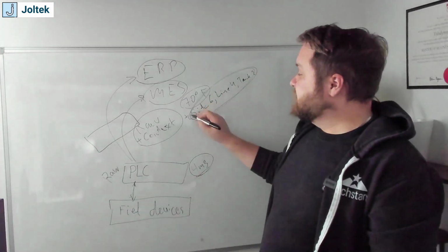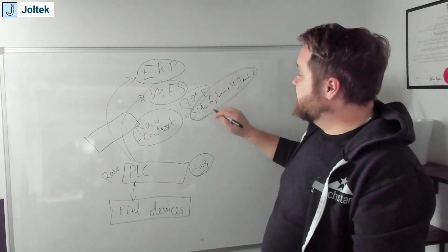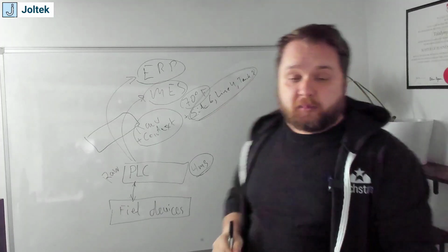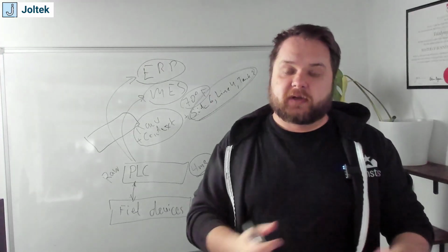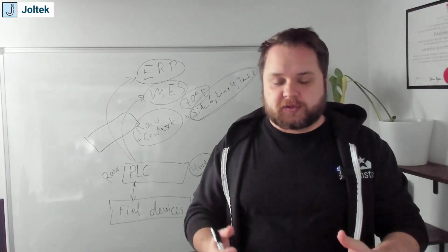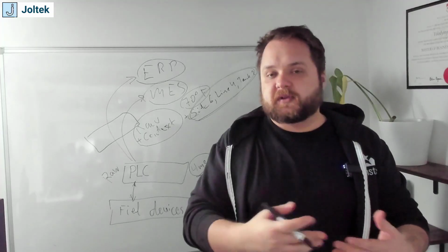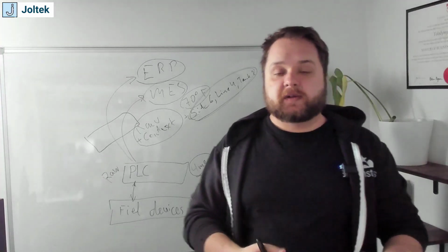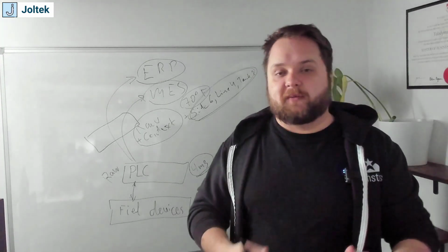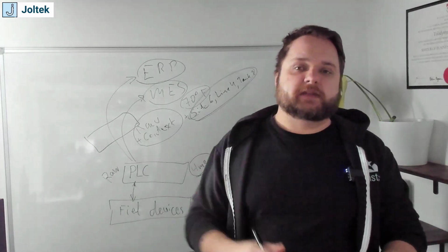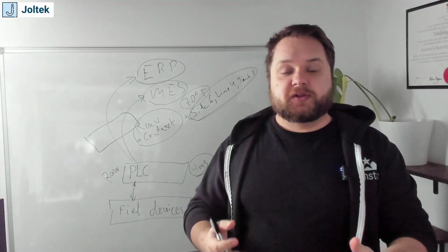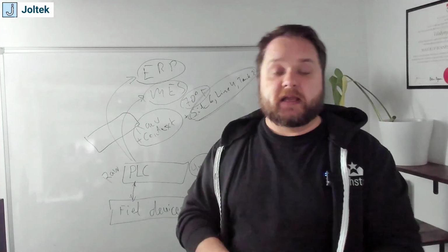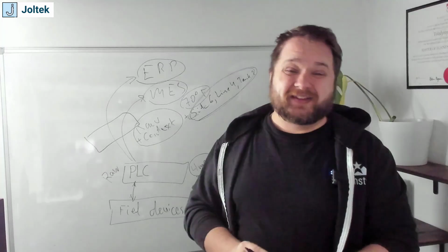And if by saying that this is a temperature, right, so this is site 6, line 4, tank 2 temperature, you are giving the necessary information for the data scientist or for AI to understand, well, typical temperatures of this tank should be within 70 degrees Fahrenheit, and they probably range from 50 degrees all the way to, let's say, 100 degrees when it's being heated. And so this is the range that we would expect. You can then apply a machine learning model to understand if it's within range.